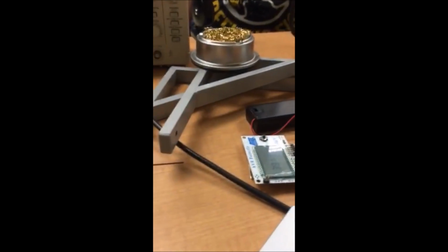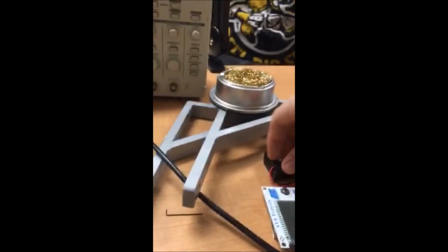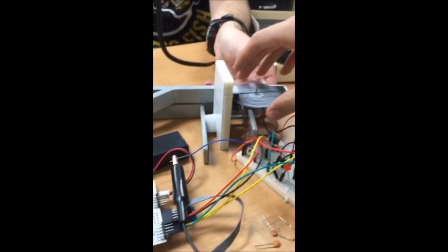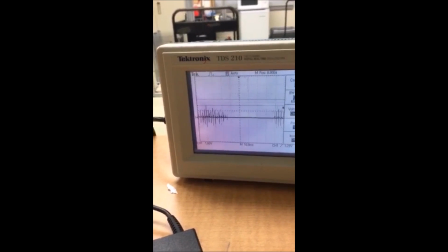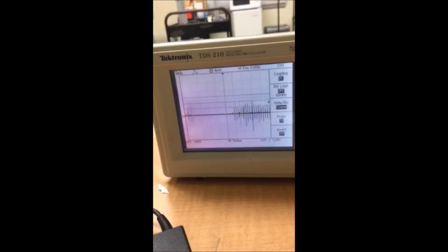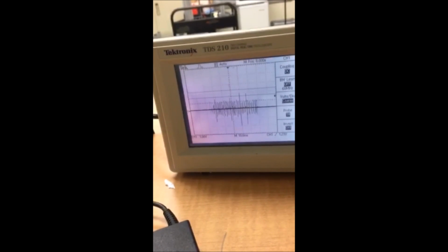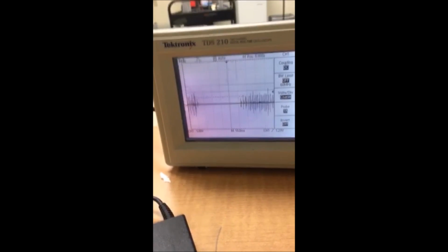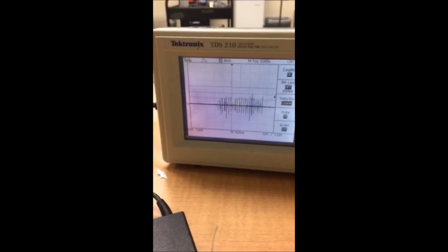I think that the reason why it might be so high is if I go ahead and take this guy off of here and run it again, I'm getting a little bit of noise on my input pin for the opto interrupter, and I think it might be triggering it. And I tried to use capacitors to get rid of the noise, but I had no luck. But I think that might be the source of the high RPMs.